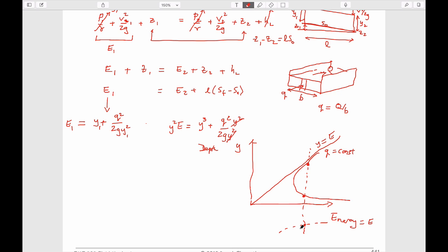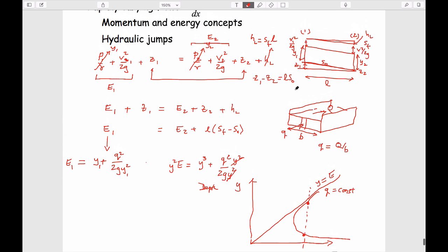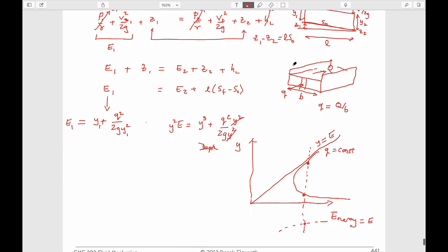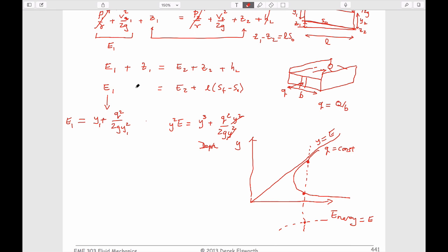And that's as far as we went last time. So I guess the point I'm making is that all we're working with is Bernoulli's equation, nothing more than that. We're just writing it in a way that's convenient for us in terms of a flow rate, which doesn't change as we go up or downstream, and with the value of this height, which is substituted for the pressure head term, which is just this component. If we do that, we can define behavior in terms of this expression here, which is one that we will use in some way, or in the way above it.